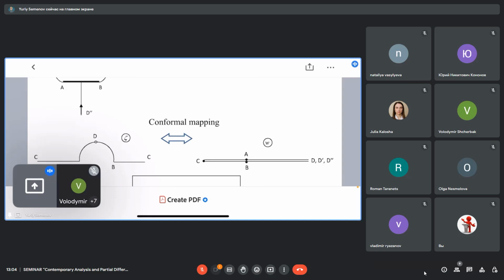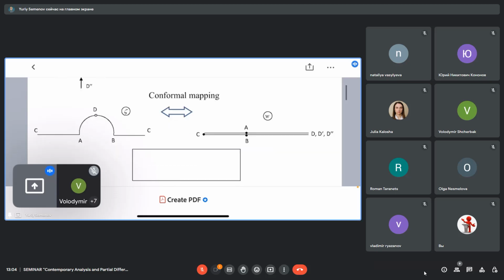As you know, complex variables are a powerful tool for solving free boundary problems. It is because the complex function satisfies the conditions of incompressibility and zero vorticity. The problem is only to find such a complex function which satisfies the kinematic boundary condition on the body and the dynamic boundary condition on the free surface, or interface, with an additional condition.